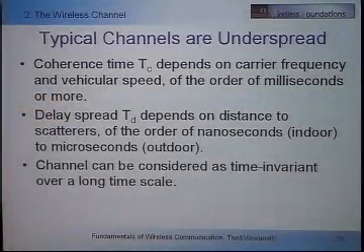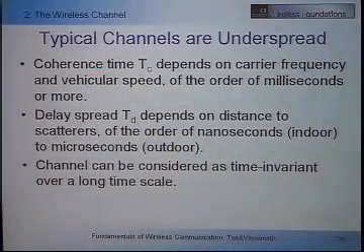However, for an underspread channel, one can think of this channel as a time invariant channel over a very long time scale given by the coherence time. And then slowly, it will change to another linear time invariant channel. The linear time invariant channel is characterized by the delay spread. That's how much memory there is. The time variation is characterized by the coherence time, but this is taking place at a much longer time scale compared to the delay spread. Delay spread, microseconds; coherence time, milliseconds. Because of this decomposition, we can use whatever we learned for linear time invariant channels and apply it to this linear time varying channel. We'll see some applications of that when I talk about communication schemes in the next section.